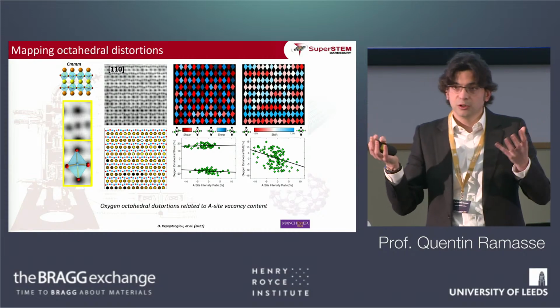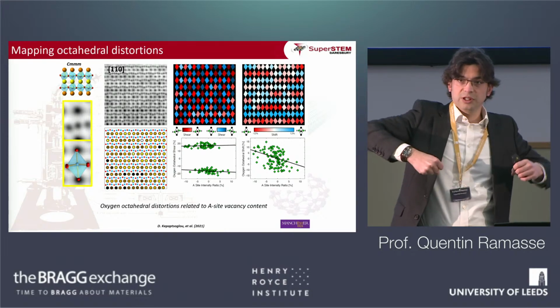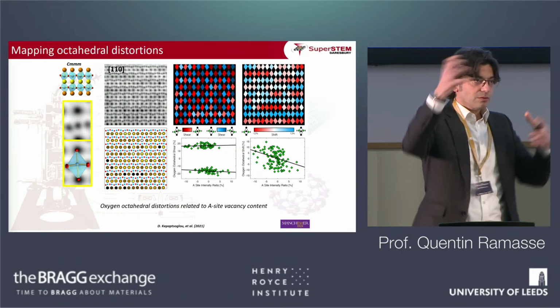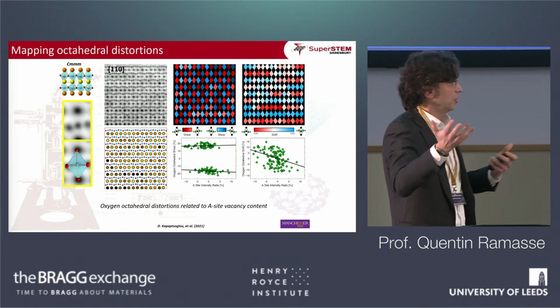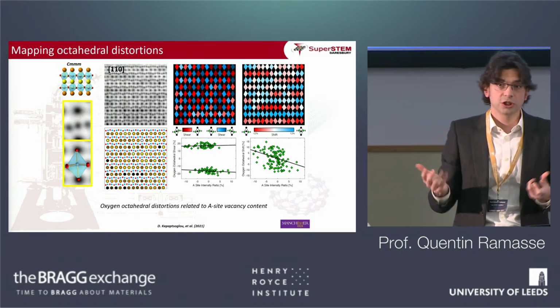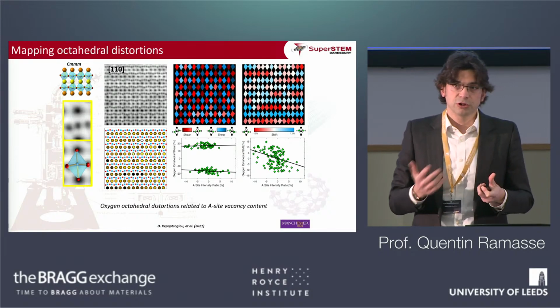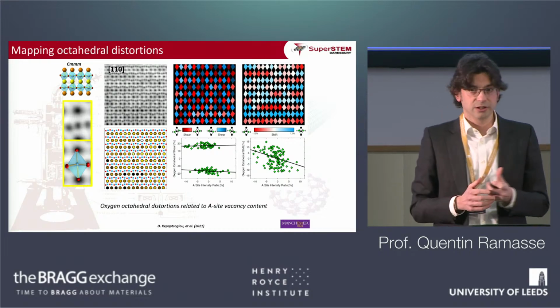Again, you understand it reasonably easily. You have something big and heavy, it needs a little bit more space to move the neighboring columns around. That somehow creates a little bit of a distortion in the material. If the neighboring atoms happen to be oxygen, and if you have an ionic material, that's going to change the local distribution of charge. If you change the local distribution of charge, maybe you change the electronic structure, and therefore you change the conduction property. So you can relate that all together.